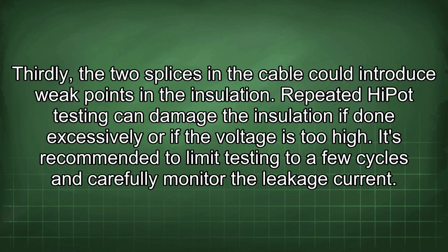Repeated HiPot testing can damage the insulation if done excessively or if the voltage is too high. It's recommended to limit testing to a few cycles and carefully monitor the leakage current.